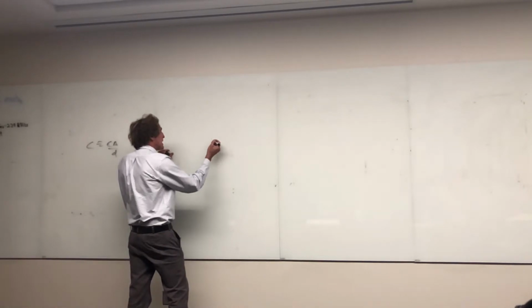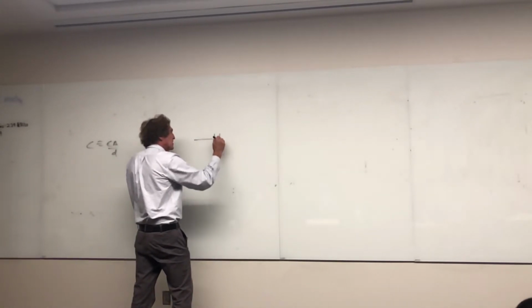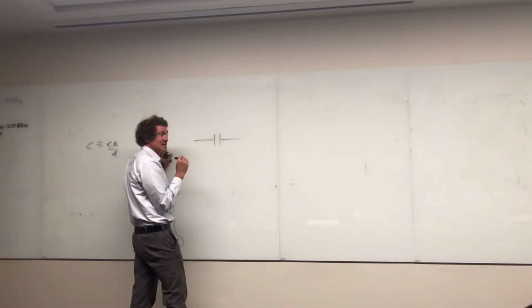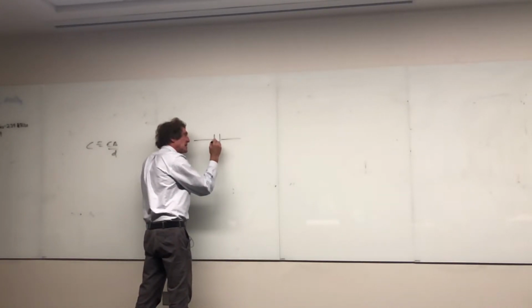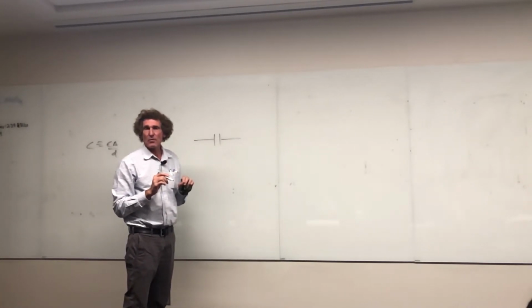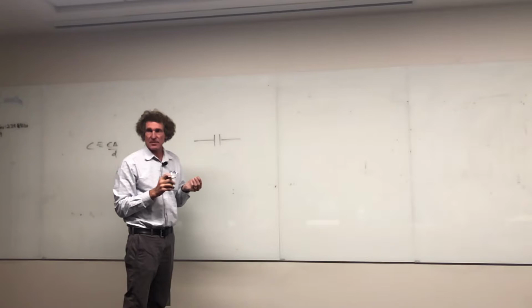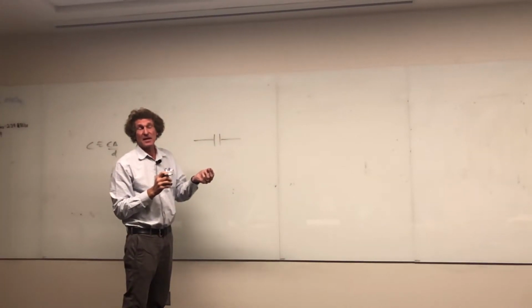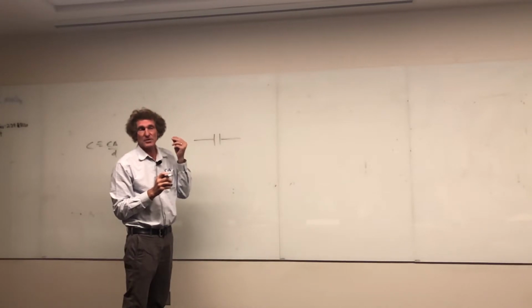The way they model a capacitor is this usually. They start with a capacitance like such, and they say that's the way it is. Now, in truth, there is some leakage resistance, but except for electrolytic capacitors, they ignore that. Most capacitors are made with good dielectrics that are not electrolytic. The reason they use electrolytic is they can store a huge amount of charge very cheaply.